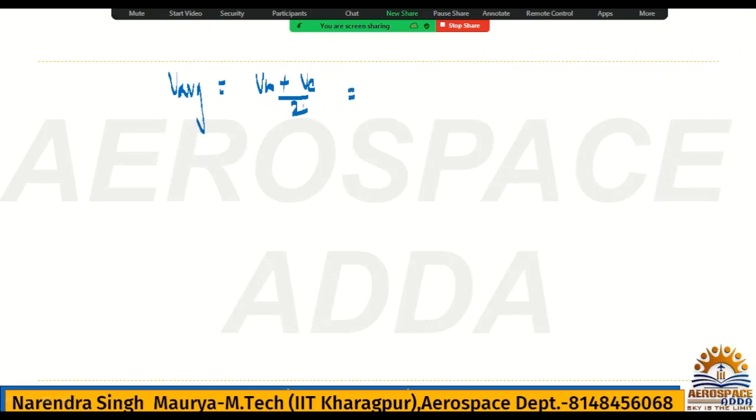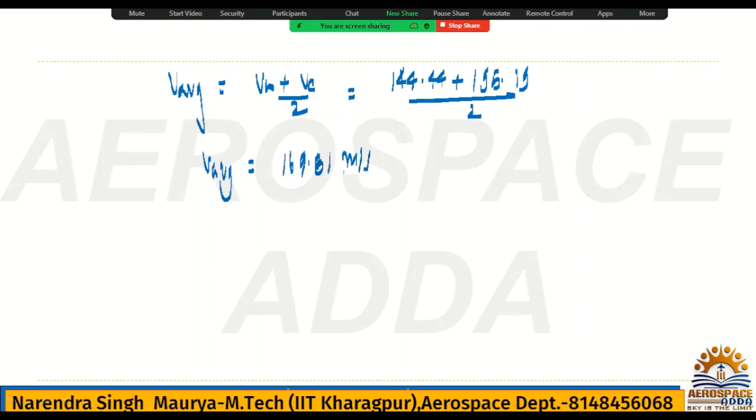So what is the V infinity? V infinity is nothing but 144.44. What is the V exit? 195.19, divided by 2. So you will have a V average, and this value you will get 169.81 meter per second, to get the mass flow rate of air.